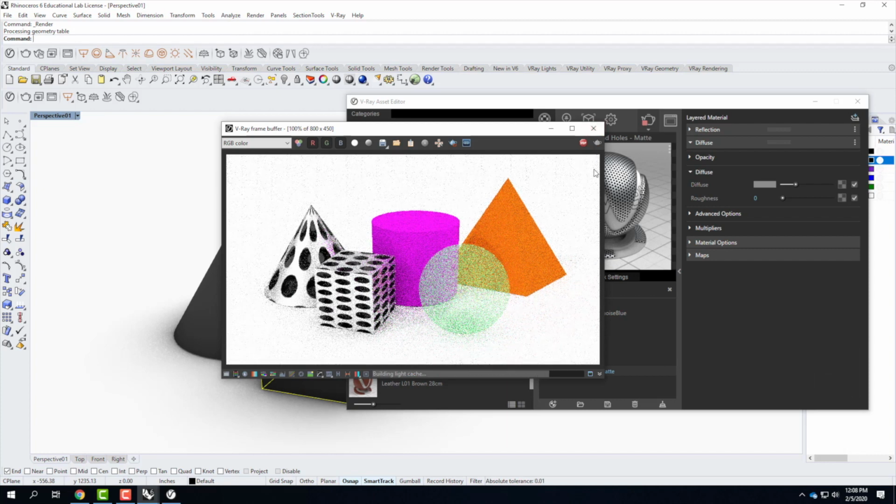So I'm going to encourage you to assign 5 different materials to your objects. So figure out how to load them in, or pick from one of the presets that's already in there, and then save your result there as well. So I'd click on the save icon and save that one. Okay? After that, I'm going to ask you to open up the building that you were working on last class. So that floor plan, remember that we extruded and put all of that in, and assign materials to that object as well. So it'll give you practice in a brand new file. When you're all done, you're going to post all of these images to the course website. This is kind of your first intro to how VRay works and how the rendering process works.